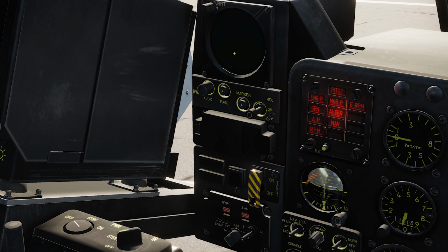The gyros are needed for the autopilot to work, because the autopilot needs gyros to know in which kind of flight state we are. We have to align the gyros with the startup. It takes about 1 minute, so it isn't that long. We can also use a test switch here, but we also need electrical power for that. So we can take a closer look later on.